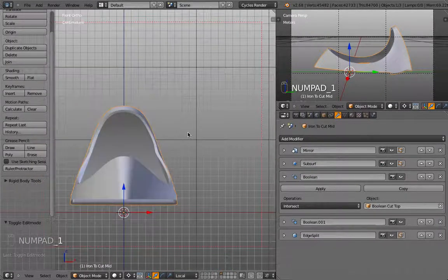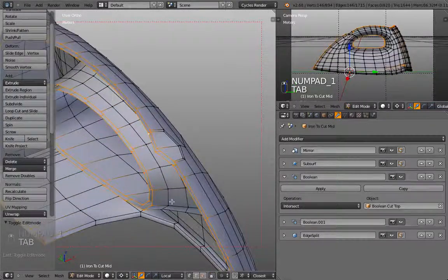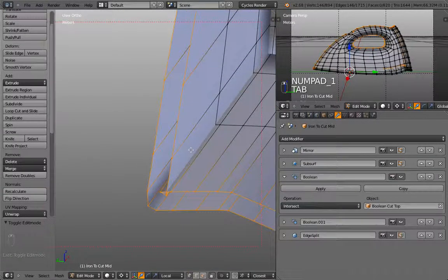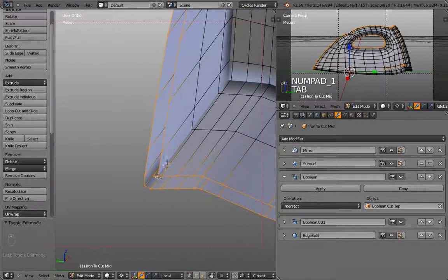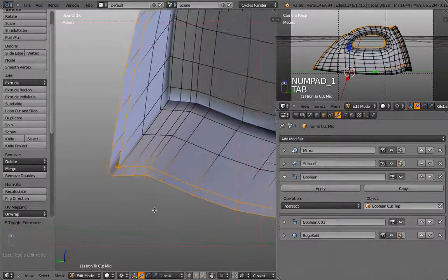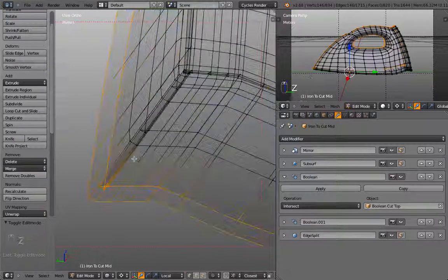The only problem I have left is there are still those overlapping geometry parts. Now, the outside of your product is really important. The inside surface is less important. And if you open a remote control at home for a TV, for example, you will see that those inner surfaces are not perfect offsets of the outside. So for example, this edge we can change or sharpen, and specifically because we here are not making a manufacturing model, but just trying to get this piece printed for our own design validation process.